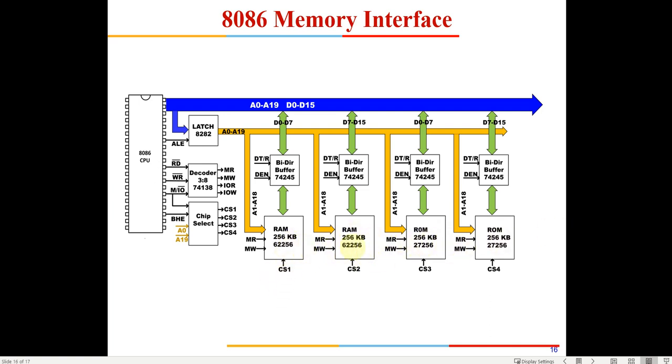So in this case I have split it into 2 equal halves, RAM and ROM. The only difference now is that for certain addresses, the first half, I want to select the RAM, and for the next half I want to select the ROM. Again, this has to be even, odd.